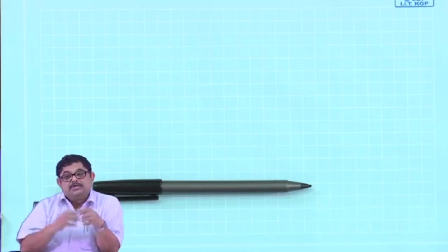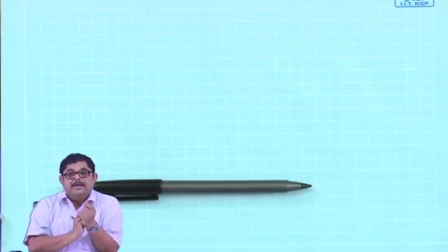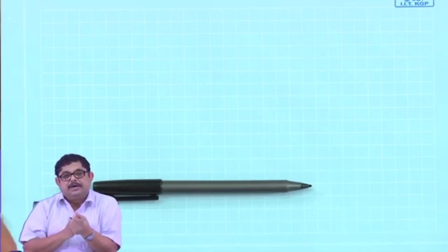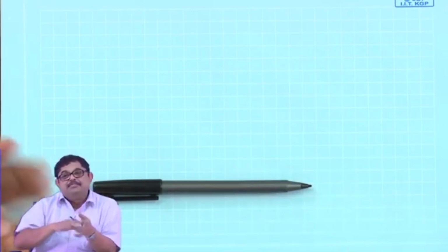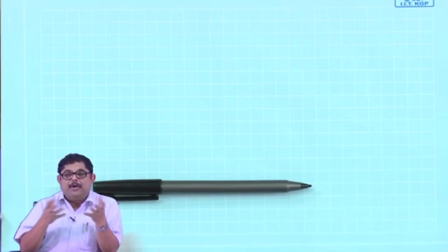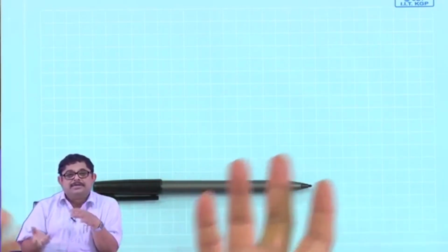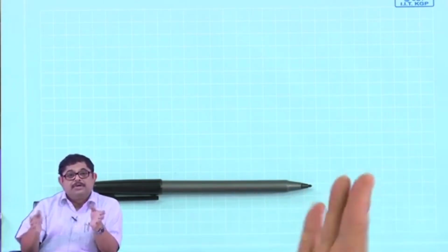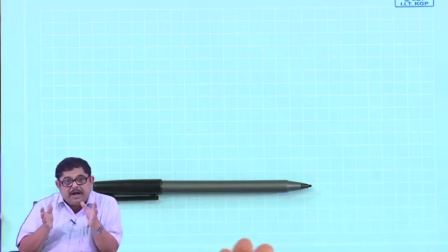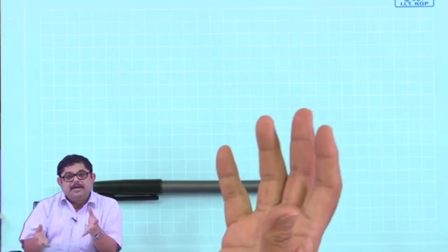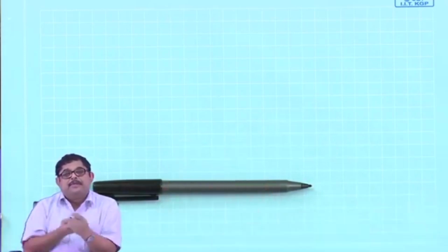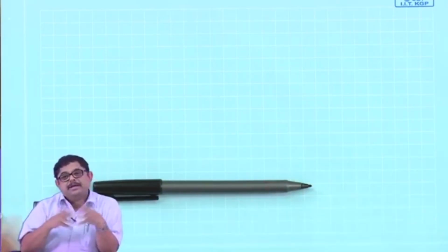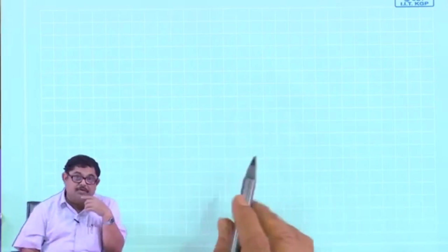So, shaping the object, but you see that if you do those types of shapings, an aircraft also has to fly. So, there are aerodynamic considerations for that, and generally making it smooth etcetera, in modern aircraft, their aerodynamics is completely opposite. Aerodynamics wants it not so smooth. So, that means this stealth requirement for shaping and the aerodynamic requirement of shaping do not generally see eye to eye. So, there is a compromise that generally needs to be made.